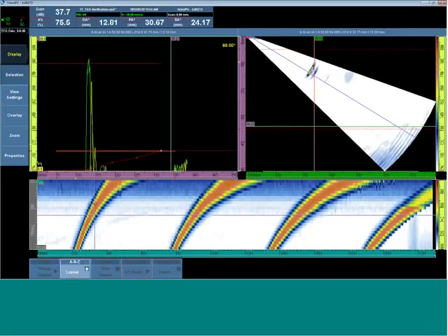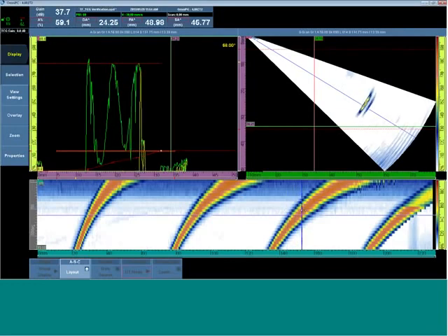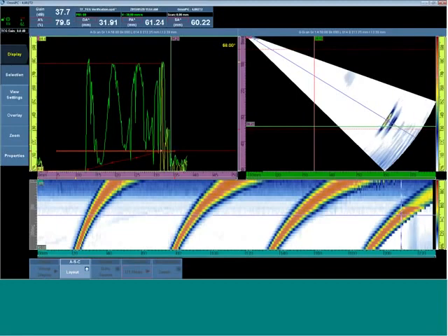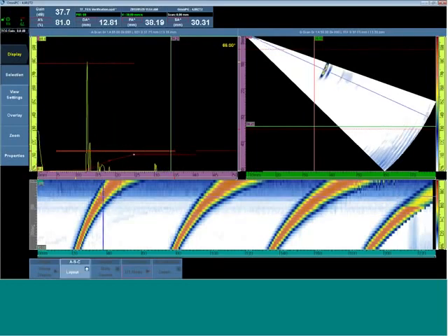If I were to drive the scanner, we can also see that any one A-scan would also have a similar, or in fact, exactly the same TCG and calibration, and this is visualized in the color palette. We're going to talk about displays later, but in all of this, we're converting color to amplitude or color to position.